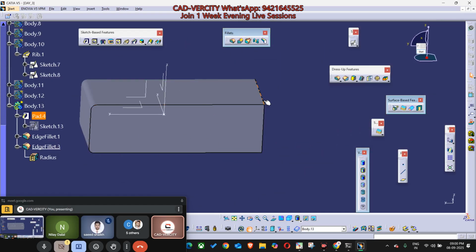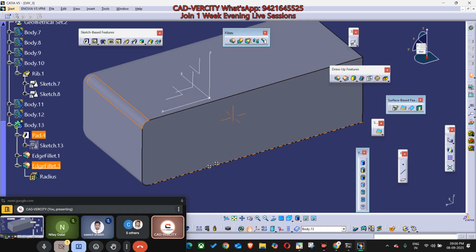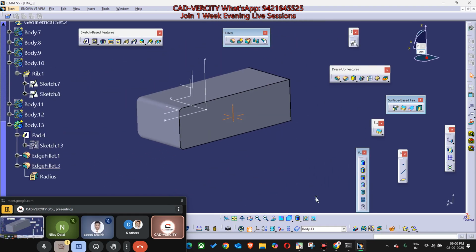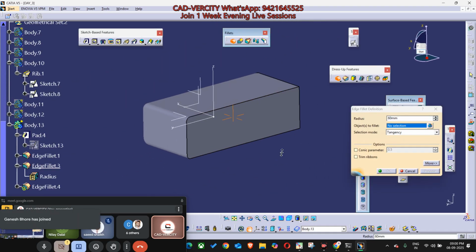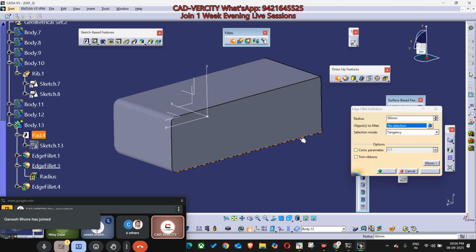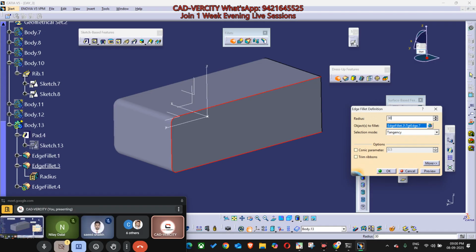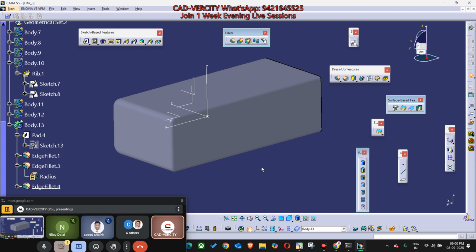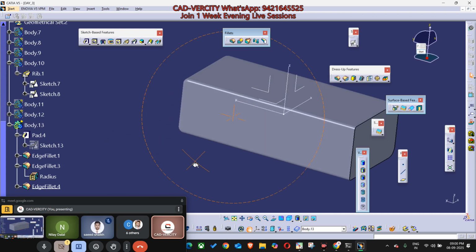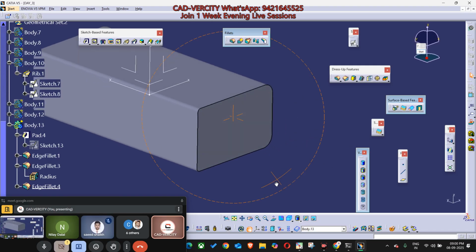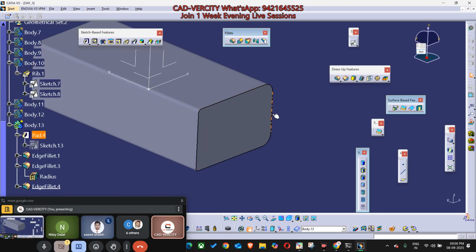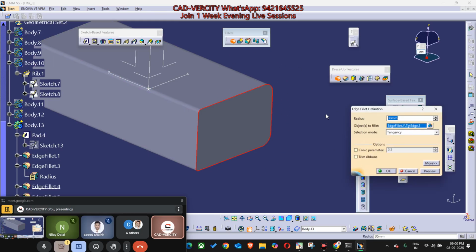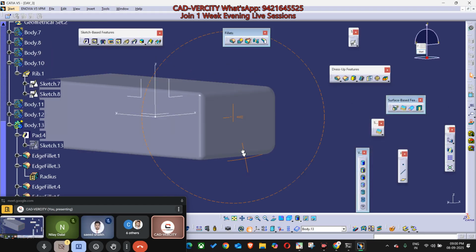Again, here you can see we have the sharp corner over here and here, but here we have the smooth corners. So even if I apply the edge fillet and give this edge as an input, it will flow automatically. Change the value to 30 mm, enter. What is the benefit of smooth edges, smooth corners? Now here all corners are smooth, so if I select this edge and the command, it will flow automatically. Change the value, make it 50, enter, done.